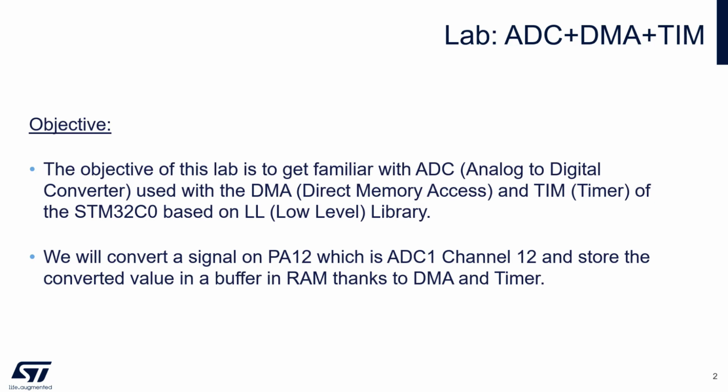During this lab, we will have the opportunity to configure the ADC associated with the DMA and the timer of the STM32C0. To do this, we will use the low-level library as I said lately. Concerning the usage of the ADC, we will connect an input voltage on the pin PA12, which is the ADC1 input channel 12, and transfer the converted value from the ADC data register to a buffer located in the RAM, thanks to the DMA and timer, which will trigger the conversion at each second.